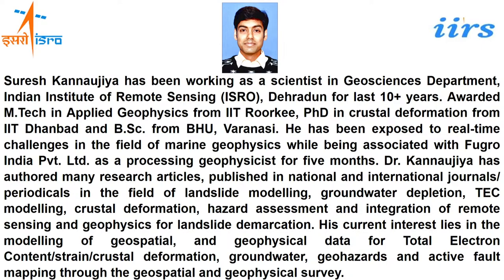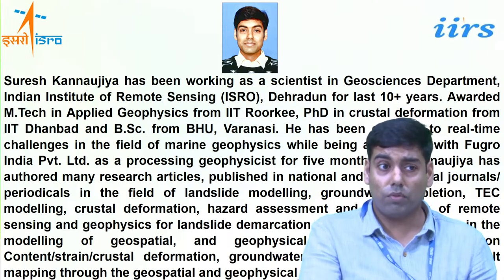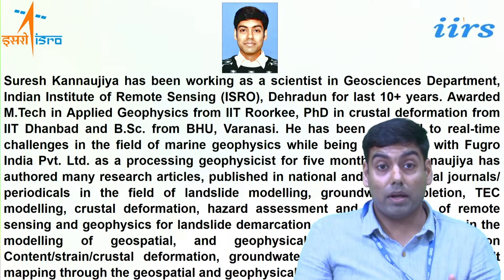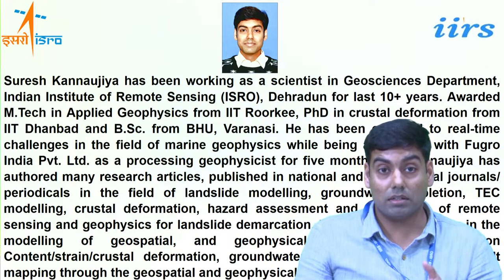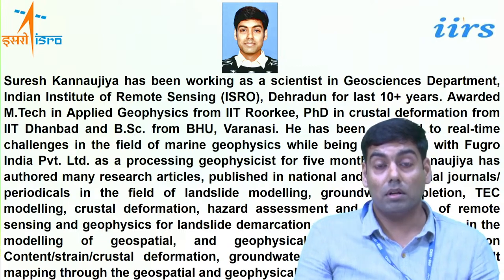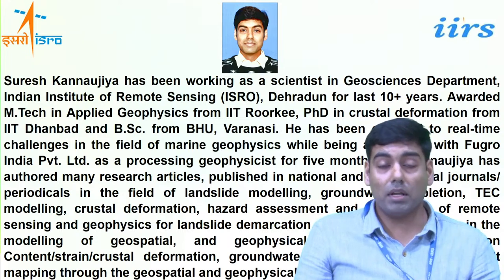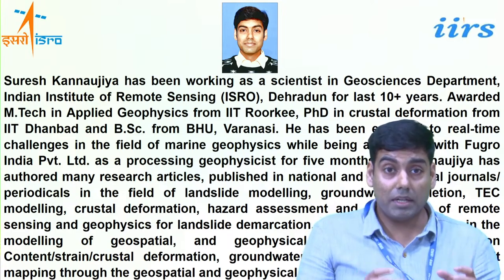We know that there are so many applications where we use this technology. We use it in fisheries, crustal deformation, active fault mapping, active fault characterization, then landslide monitoring, subsidence monitoring. Then you are going for GCP collection. You want to validate something, or if you want to make a digital elevation model, then you need very accurate latitude, longitude, and height information, so that you can do the ortho rectification and implement this data during digital elevation model preparation.